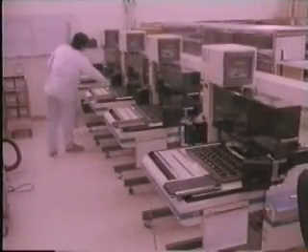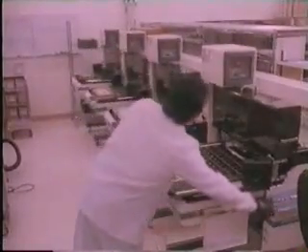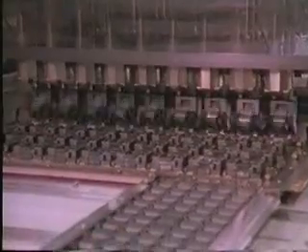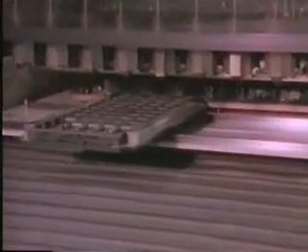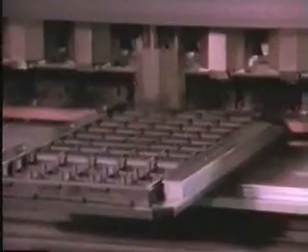The individual chips now undergo testing. They are loaded onto burn-in boards which will be placed in ovens. These boards consist of many electrical sockets. When connected, they allow electrical contact with each chip. In these boards, the chips will be stressed far beyond normal conditions. Weak chips are forced to fail prematurely before they are put into a customer's product.